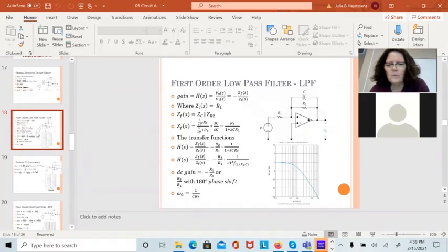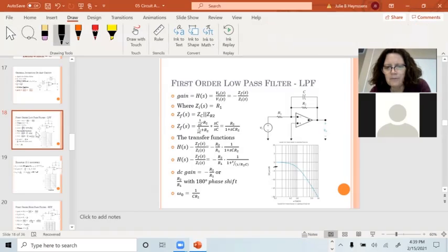So wherever I get 3 dB below that peak value, whatever it is, that is my 3 dB frequency, a term you hear a lot out in the real world. And the omega value down here should be my omega naught.